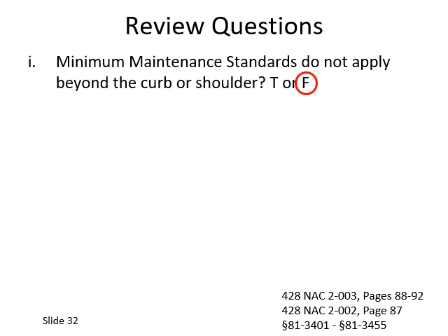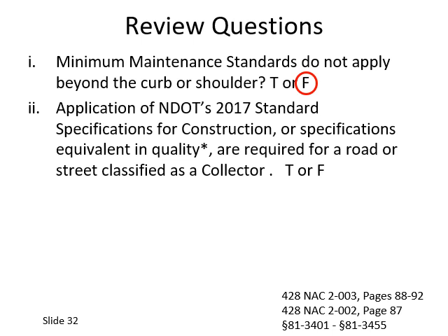Question 2. Application of the Nebraska Department of Roads 2007 Standard Specifications for Construction, or specifications equivalent in quality, are required for a road or street classified as a collector. True or false? The answer is true. It is true for any functional classification above local, which means collector, other arterial, major arterial, expressway, and interstate. It may also apply to federal aid projects.